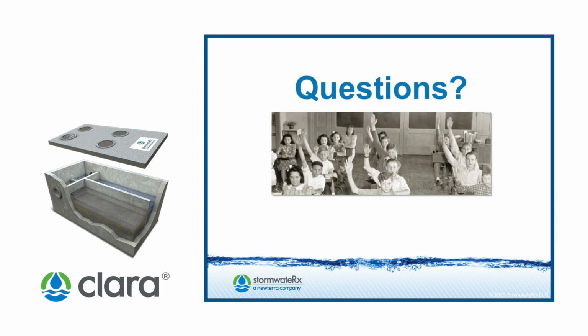Hi, Sharon. I wanted to maybe address your question in chat. Thank you for joining us too, Sharon. I noticed only loadings of TSS under 100 milligrams per liter is shown. The site with high TSS loading sees sometimes 400 plus. Was there any testing with this type of loading? No, there wasn't. Like Rob mentioned, we got what we got in terms of the stormwater that we ran through the pilot. I would suspect that sites that had a TSS greater than 400 would require more maintenance.